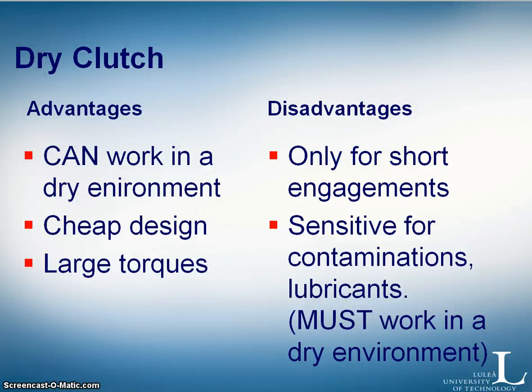You can smell it when you are driving the car, if you're trying to park a heavy trailer or something, that it starts to smell. If you are working a lot with the clutch, at slow speeds and high torques, you overheat the clutch. It is also sensitive to contaminations like lubricants.